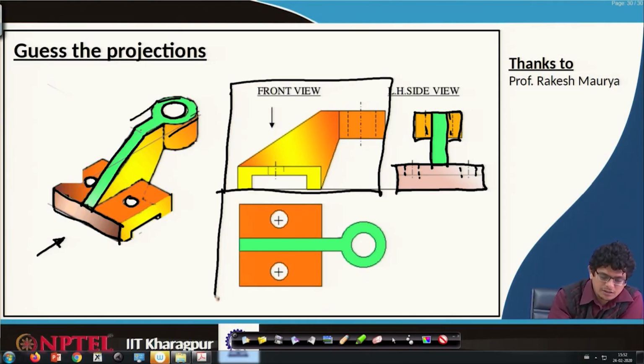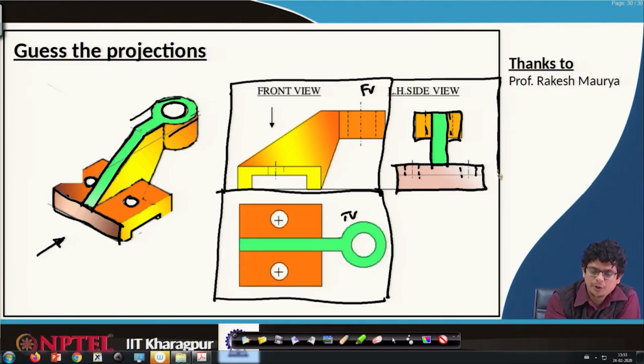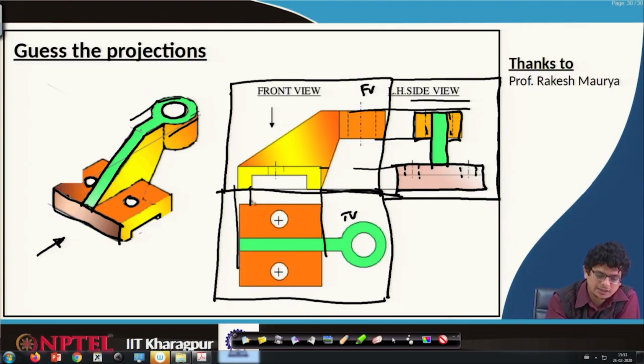Below that, with a certain gap, which we have seen, varying from 4 millimeters all the way to 25 millimeters, separated by the top view, front view, and again there is a perpendicular box which comes on the other side for your side view, and these projection lines are supposed to get matched. Similarly, these lines, such kind of things we are supposed to see.